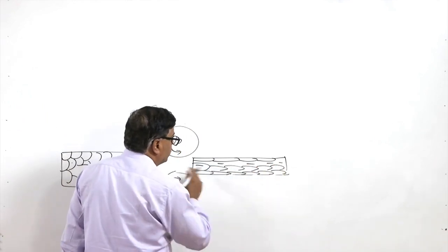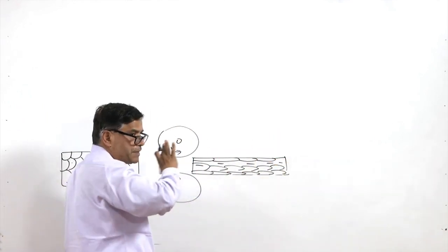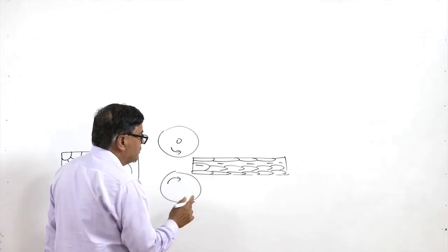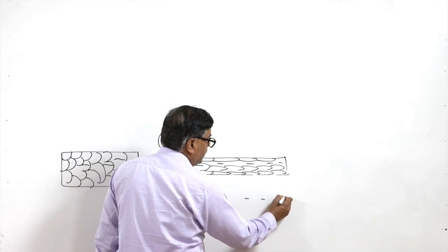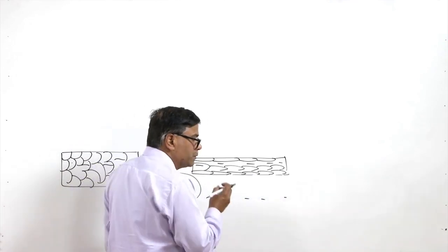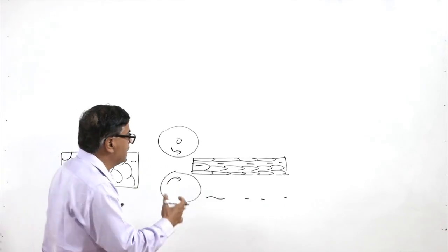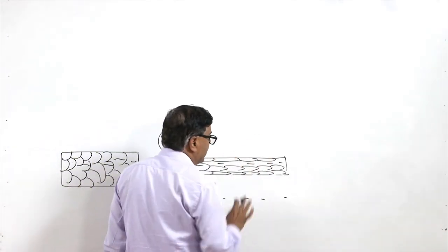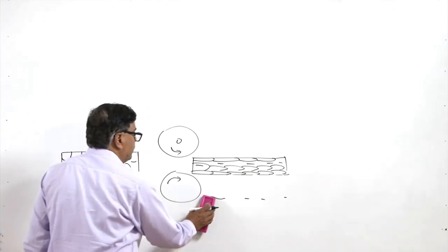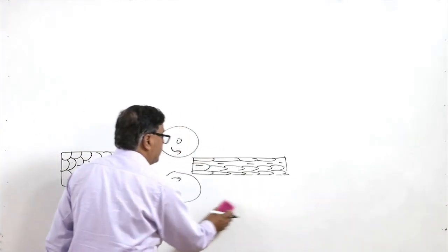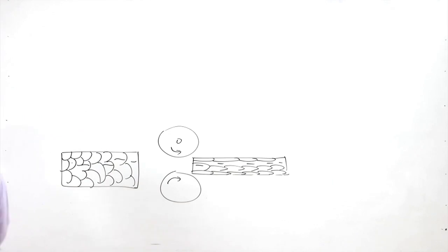Due to the extensive plastic deformation in the direction of flow of the material, the inclusions get broken down into small pieces. The inclusions will be present in a very discrete manner throughout the entire mass of the metal. That in turn will reduce the severity of the effect of the inclusions.